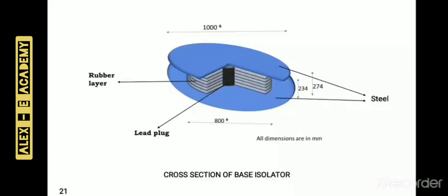The lead rubber bearing effectively dissipates the inertial force upon the building, extends the building's period of vibration, and decreases the acceleration of the building. The lead plug will slide with laminated rubber during earthquake but convert this energy of movement to heat. Meanwhile, the rubber part will preserve its original shape due to high elasticity. This is a practical and cost-effective choice for seismic isolation.